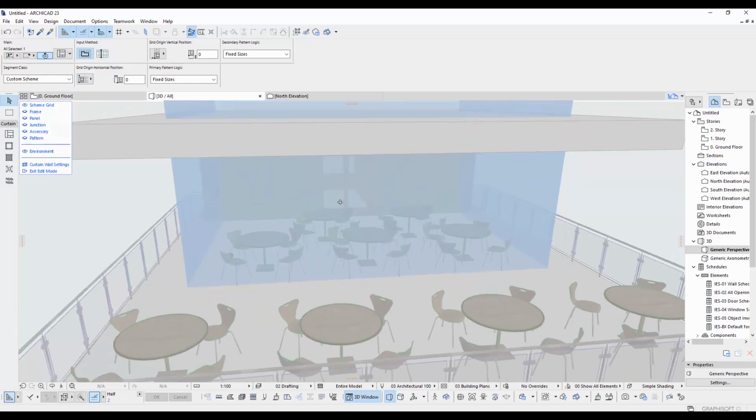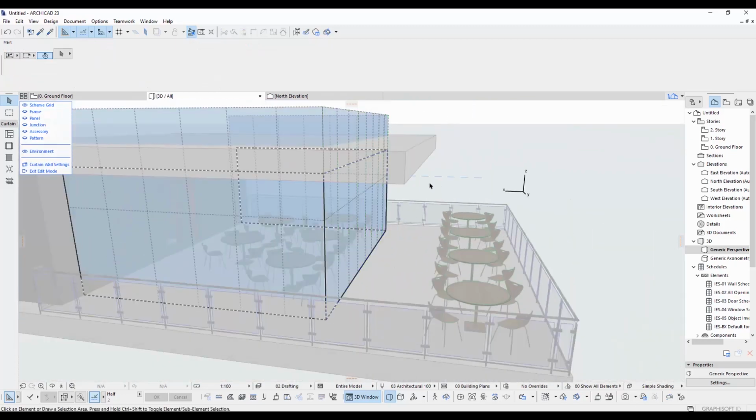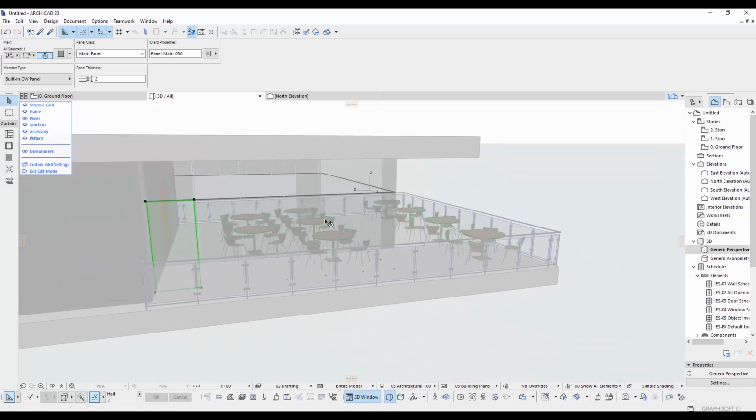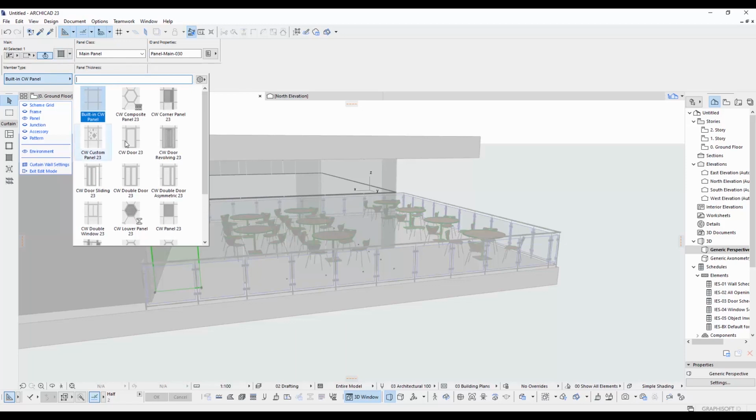I'm gonna add two entrance doors. I need to convert some panels to door. If I right click the panel, it will be isolated in 3D and I can turn the panel to a door or any pattern which I selected.